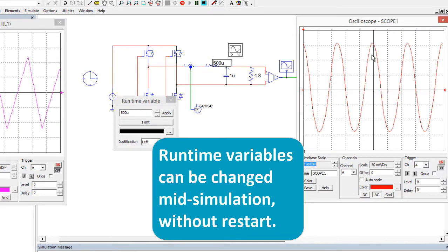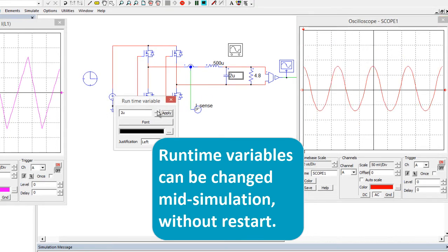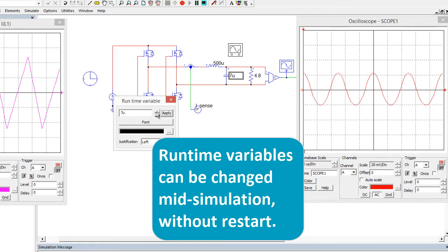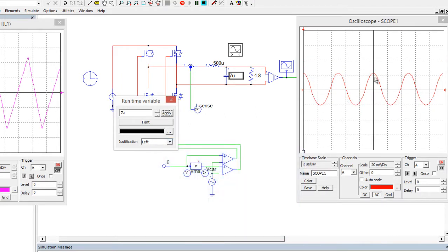We're looking at 200 millivolts, so maybe we need a little bit more capacitance. So what's that now? 20 millivolts, maybe a little bit more. So that is 40 millivolts peak to peak on 120 volts, which I think should be okay. Let's go with that. So 500 microhenries and 7 microfarads.